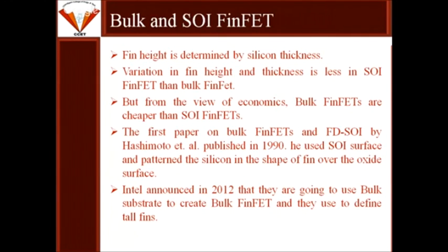The first paper on bulk FinFET and FDSOI was by Hashimoto et al., published in 1990. He used an SOI surface and patterned the silicon in the shape of a fin over the oxide surface. While Intel announced in 2012 that they were going to use a bulk substrate to create bulk FinFET, and they used it to define taller fins.